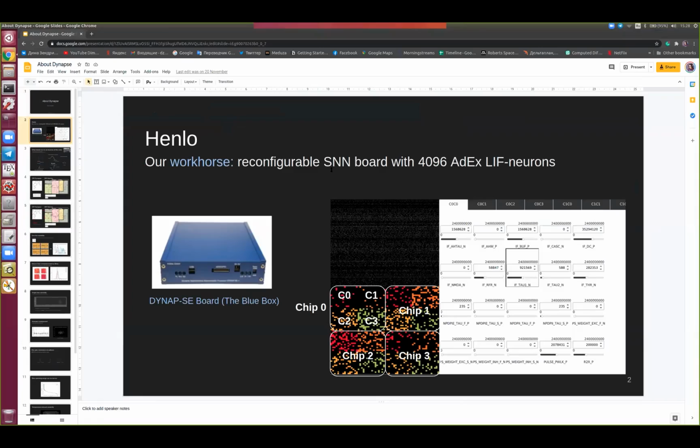So this is basically a chip that contains 4,000 of these silicon neurons with 4 types of synapses, and they are organized over 16 different cores. For every core, you have direct access to the biases. I think you should have learned at least some of the aspects of how you would bias the neuron circuit.